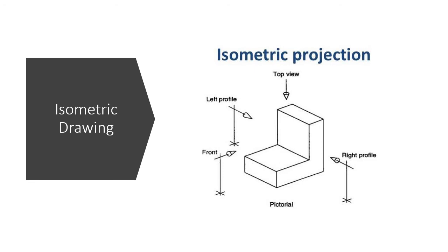Isometric projection, as we know it, has been used for centuries, until it was formalized, and rules on how to draw an isometric drawing were created by Professor William Farish in the 19th century in France. It has been an invaluable tool for architects, engineers, and designers to use in their work. An isometric view of an object can be obtained by choosing the viewing direction such that the angle between the projections of the x, y, and z axes are always 120 degrees.